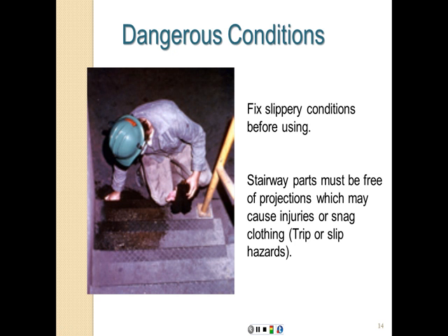So this is basically what it takes to know about stairs. Now we're going to talk about ladders. So from stairs we learned about the 19-inch difference in elevation. We learned about 4 steps or 30 inches. You must have a handrail or a guardrail. We learned about the slope of the stairs between 30 and 50 degrees. We talked also about the difference in the height of the stairs or the depth of the tread, no more than 1/4 of an inch to provide uniformity.